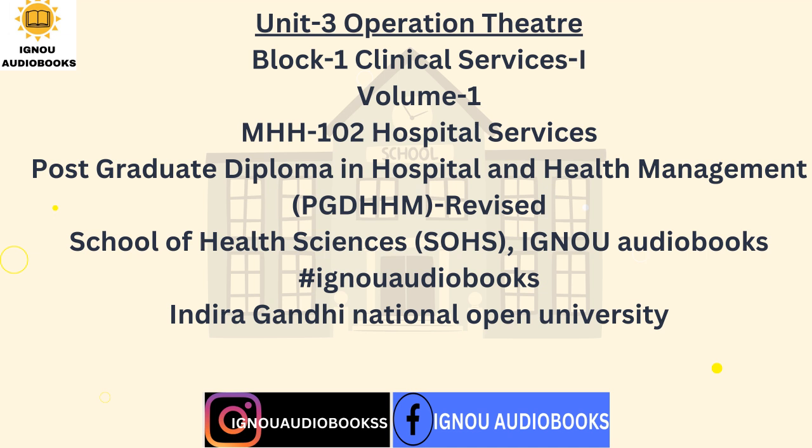Modern air treatment plant for an operating room consists of a blower to move the necessary amount of air, a pre-filter to remove particles, and an air conditioner which heats, cools and dehumidifies or humidifies the air. Current standard requires for operating room air a minimum of 12 to 15 air changes per hour, positive pressure compared with corridors, temperature between 18.3 and 23.8 C, 65 to 75 F, humidity of 50 to 55%, and depending upon the locality, up to 80% recirculation, with the use of effective filtering. In some cases, even 100% outside air with no recirculation is suggested for the purpose of sterility and infection control in the operation theatre.